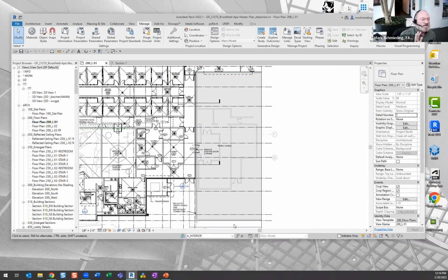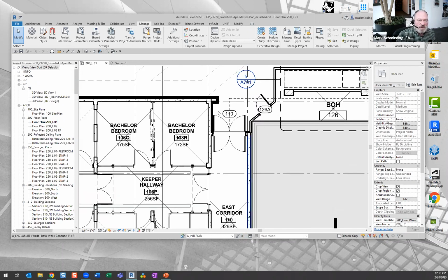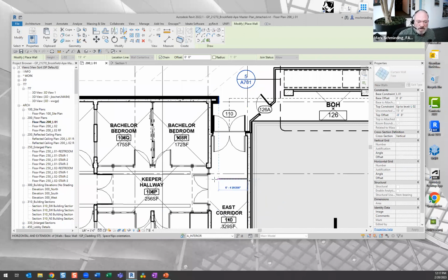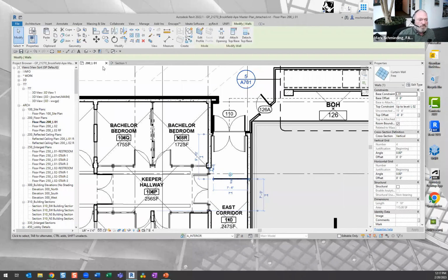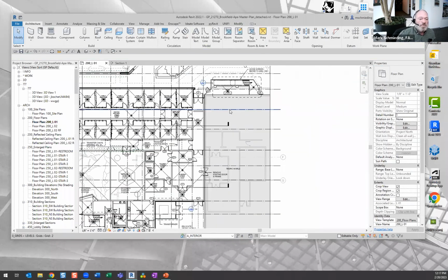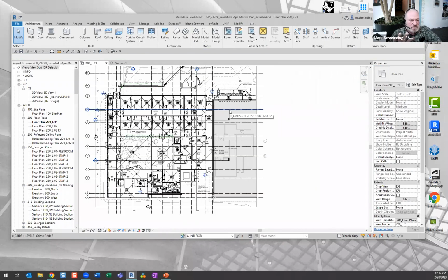This is the thing, it's in plan, right? I can place that CAD file there, and then I can come in, I'm just going to do it here, say I go architecture wall, and then I could start adding wall types here. So if you have an existing CAD plan, and then if you had CAD elevation, etc., you can have a hybrid approach. So if I had the plan in CAD and then I just wanted to start using the elements in Revit, I can have both of them in this information.